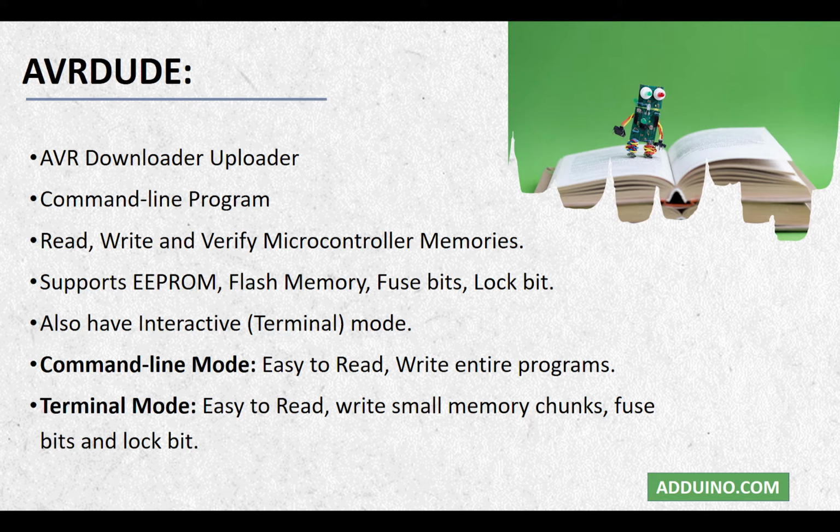There are also some other third-party GUI packages for AVRDUDE, which are handy if you are not comfortable with the command line. However, the command line program is recommended, and you can easily automate the build process using a makefile, which we will discuss later in this course.